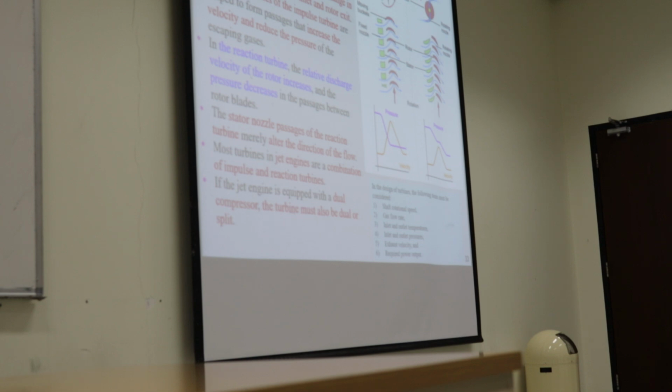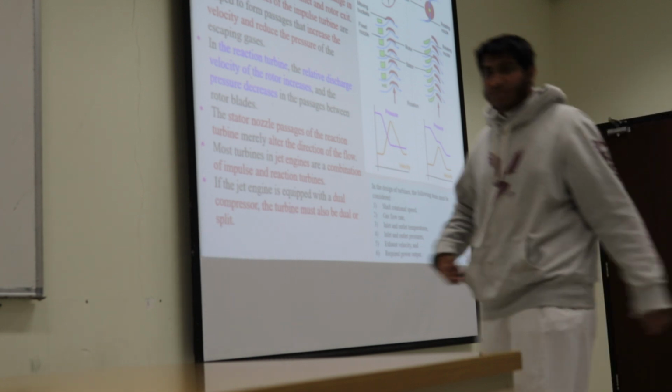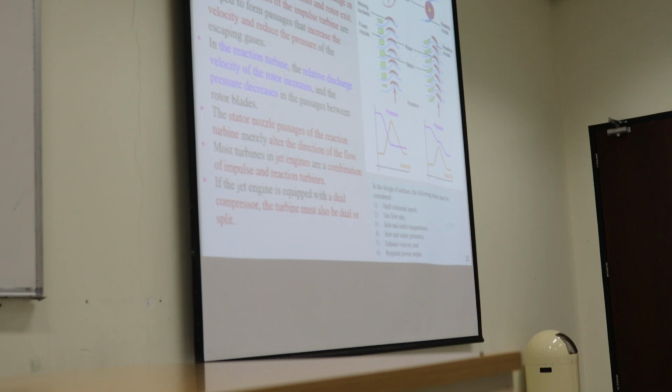So Shabab, look at the moving blades here for the impulse and reaction turbine. The moving blade in the impulse turbine takes the shape of a bucket, so it is symmetric. Look at it. Where does the flow hit? It hits almost at the middle, so it doesn't have contact with the surface of the blade itself. So the idea here is just an impulse, a hit. The flow will hit and then leave. That's why, if you look here, we don't have expansion. As a matter of fact, the pressure is fixed in the moving blade.